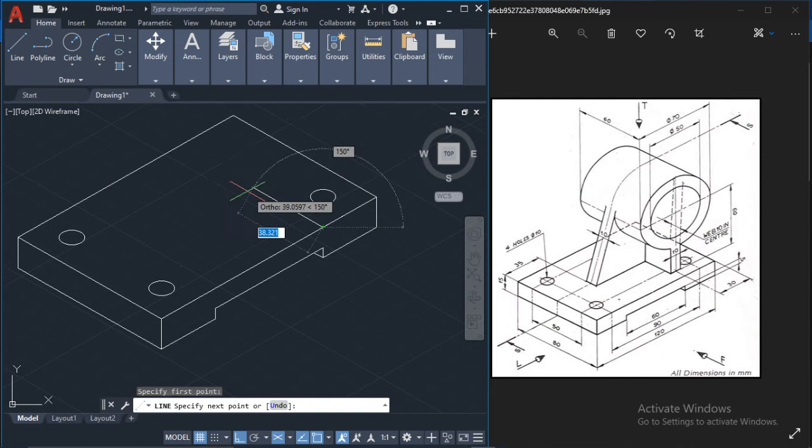So now I can bring this line across, and let me see if I see the measurement of how much this goes across by. All right, so it says that the total distance for this circle here is 60, and this line is here. This tells us that it is symmetrical. So if this total distance is 60 here, and then this total distance is 80, that means that there's 10 millimeters of space here and 10 millimeters of space on the next side. So that means that this goes in by 10. So that's the point that we're looking for now.